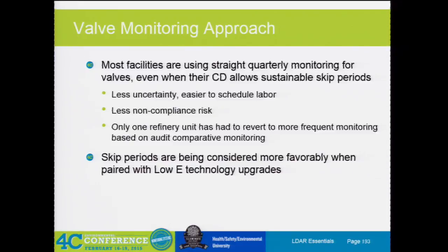Valve monitoring approach. Most facilities use straight quarterly monitoring for valves, even when their CD allows skip periods, like I said. Less uncertainty, easier to schedule labor, less non-compliance risk. And so with that, and this is actually a slide I put together, I've already talked about it, you're managing your level of compliance risk. Like we said earlier, if something goes bad, you're the one that's going to be getting talked to. You're the one that's going to have the red face test, correct?